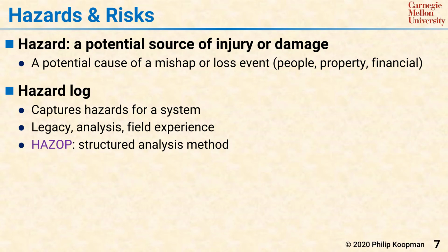For example, if there is a requirement for speed, a HAZOP would modify the wording of that requirement with keywords such as too fast or too slow to help in brainstorming what might happen if the system was faster than the required speed or slower than the required speed.